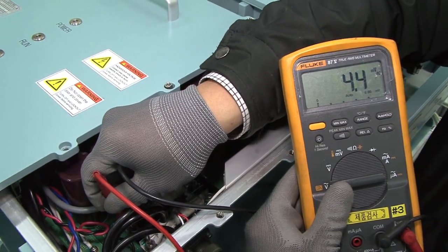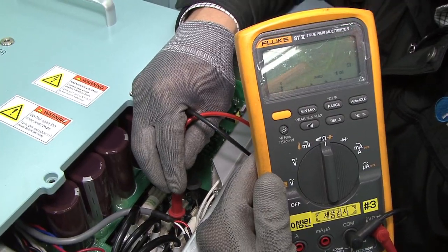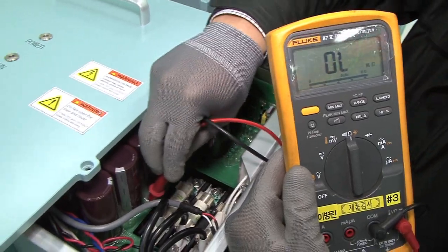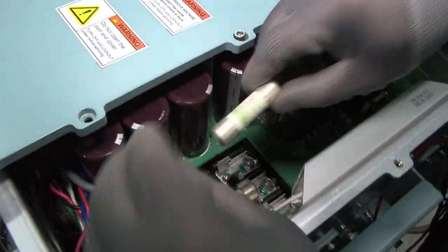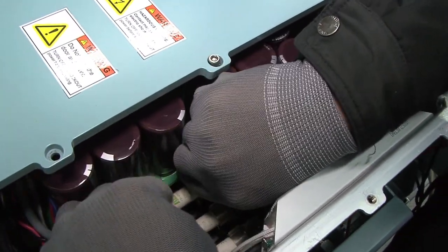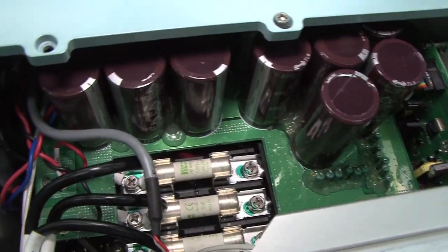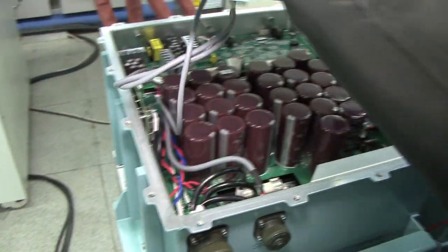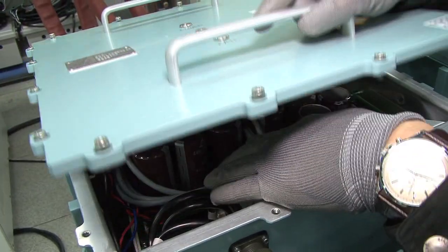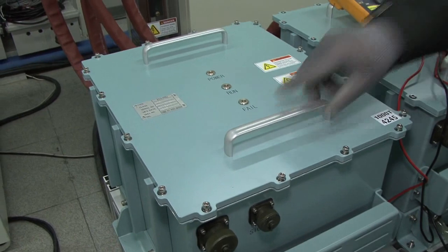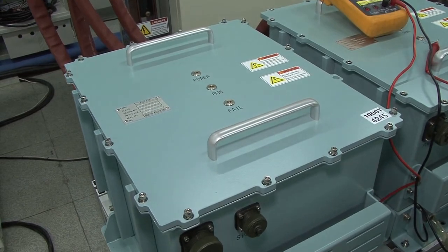Step 3. Check connection of fuse, 1A, of R, S, and T with a tester. Step 4. Remove defective fuse with driver. Step 5. Assemble new fuse at the fuse holder. Step 6. Check the order of lamp wiring of power, run, fill lamp and assemble connector. Step 7. Close the cover after arranging the lamp wires evenly in the capacitors. Step 8. Tighten the cover with bolts. Step 9. Check if power lamp light is working properly.